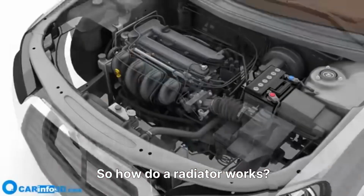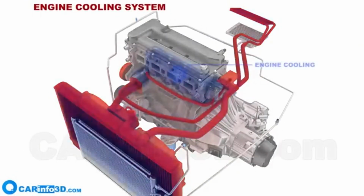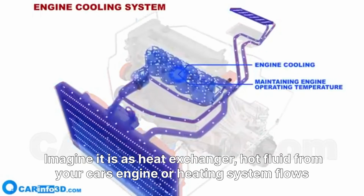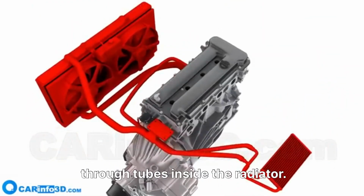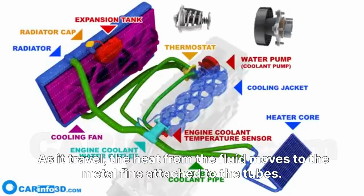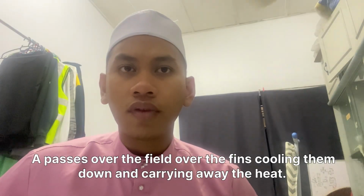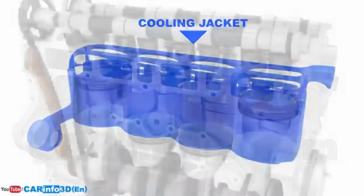So, how does the radiator work? In simple terms, a radiator works like this. Imagine it as a heat exchanger. Hot fluid from your car's engine or heating system flows through tubes inside the radiator. As it travels, the heat from the fluid moves to the metal fins attached to the tubes. Air passes over these fins, cooling them down and carrying away the heat.